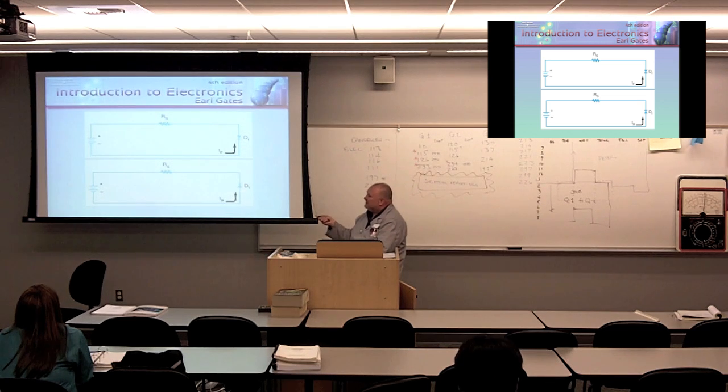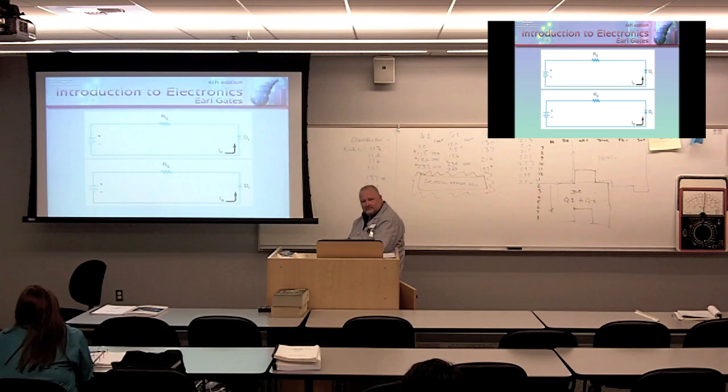This right here is a silicon diode. What voltage drop will I get across this resistor in this condition? This is 12 volts applied. So what voltage am I going to have across this? What's that? 0.